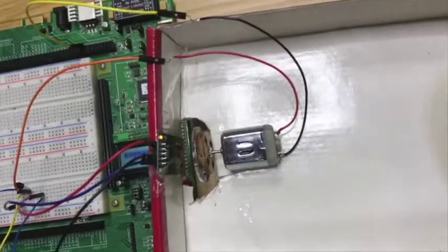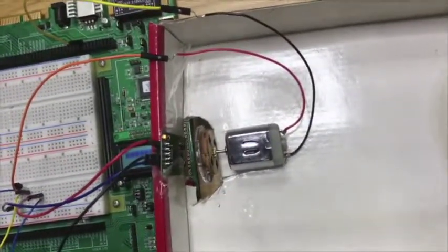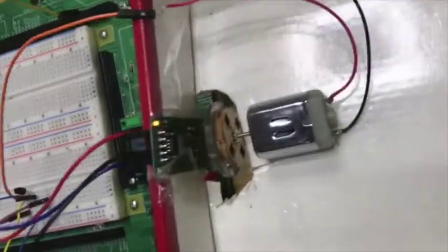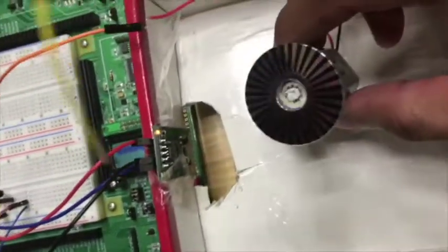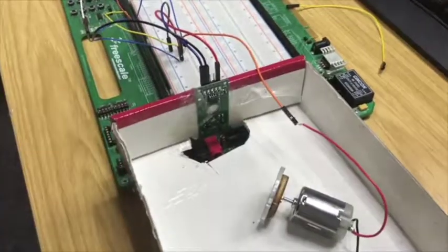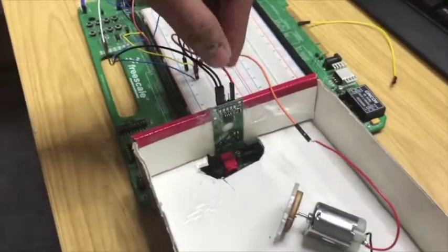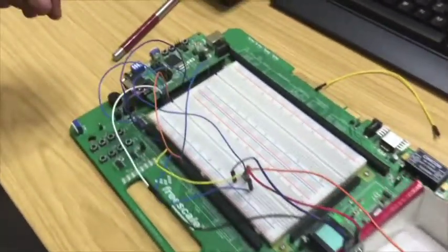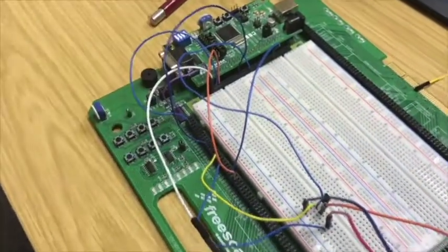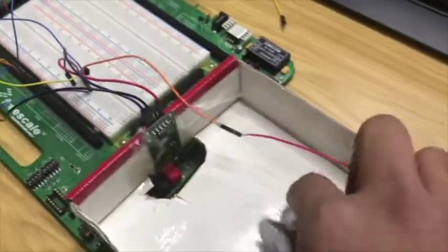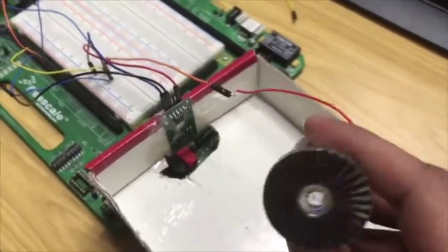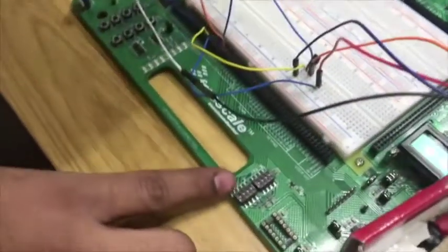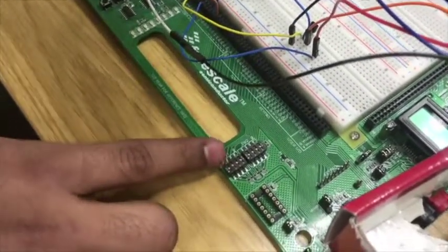The DC motor represents the wheel of a car, and we have mounted an optical disc onto the DC motor to note down the speed at which the DC motor is spinning. The optical encoder generates a square signal based on the reflection from the wheel, and the square signal is fed into the timer input capture, and we use it to calculate the RPS, that is revolutions per second, of the DC motor. This switch is used to turn on the cruise control.